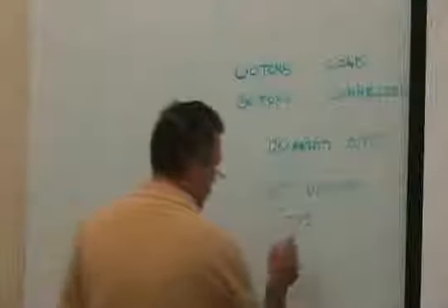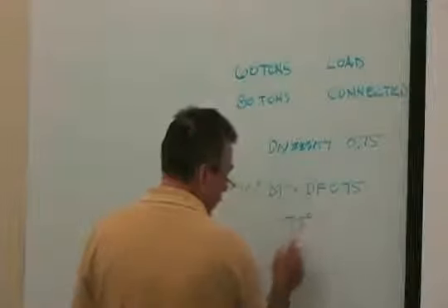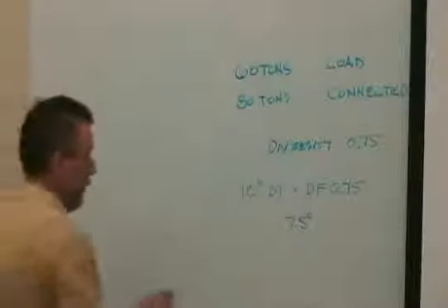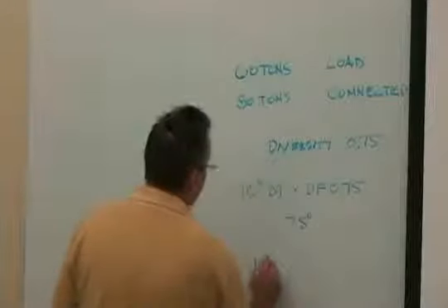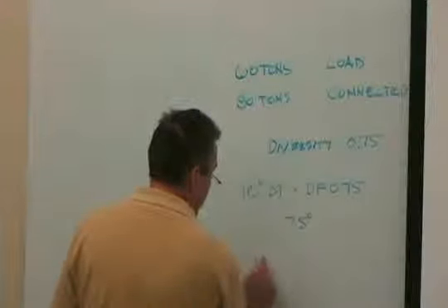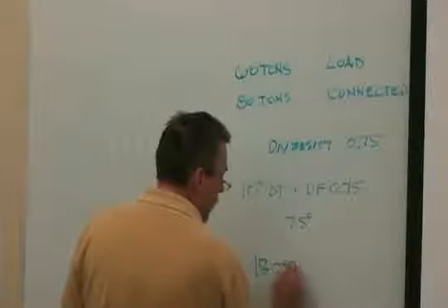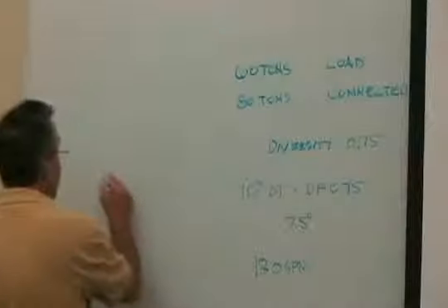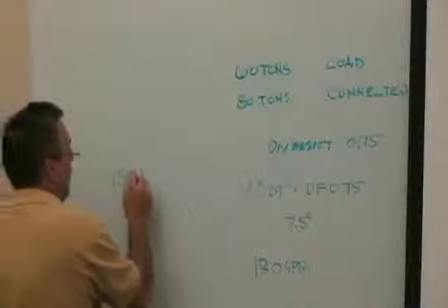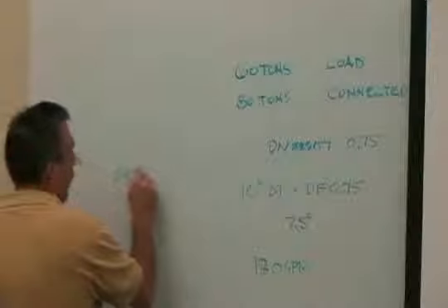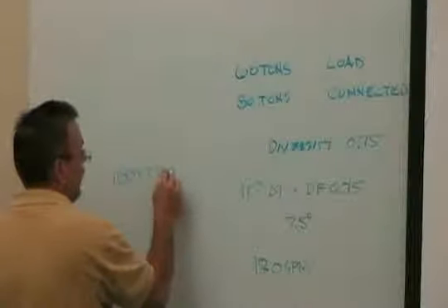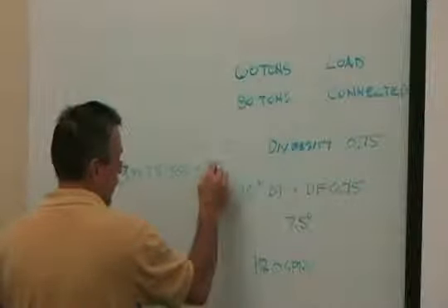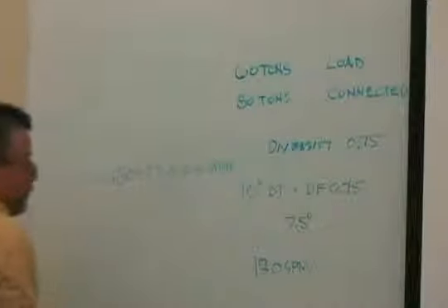Plus my air water temperature of 90 or 80, whatever it is. So I can actually select, I've got 60 tons, so I've got 180 GPM maybe as my flow. And I want a 7.5 degree delta T, so 180 times 7.5 times 500 is equal to BTUH. There's how I size my fluid cooler.